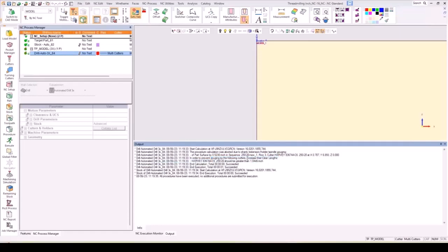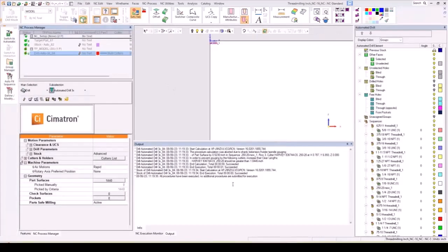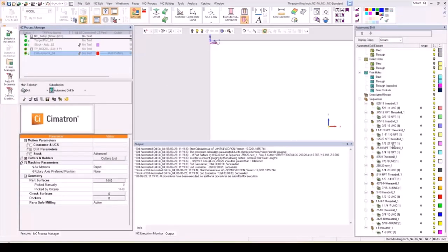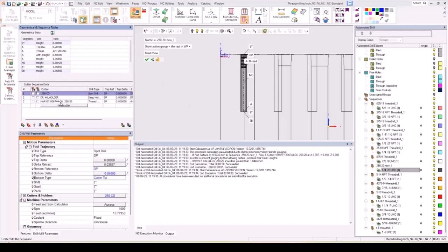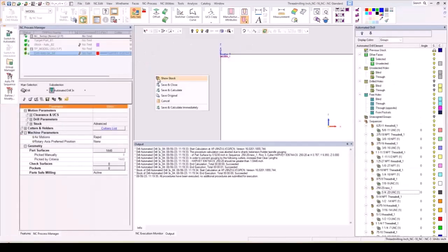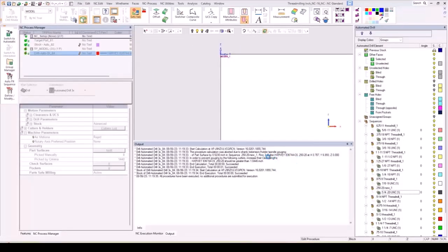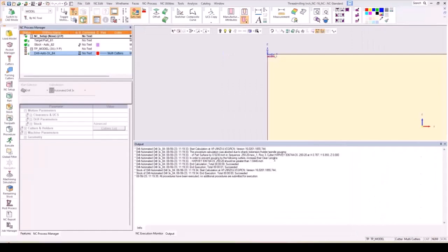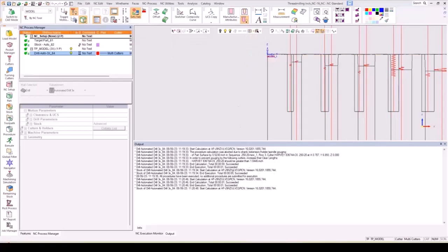So in this case, I go to sequence 1/4-20, I go to row 3, and this is the tool. So it actually tells me exactly where 1/4-20 goes to this cutter, and then it tells me, hey, you're too deep, the tool's not long enough. So in this case, we'll just put it back because we already knew it was fine here. But now when it goes through, we won't get this error anymore. So we'll get the motions, and we're all clear here.